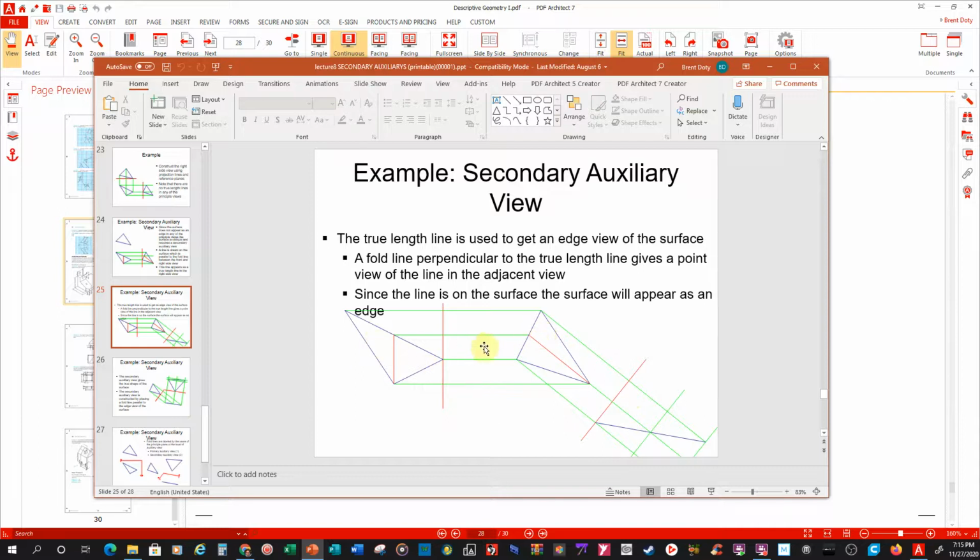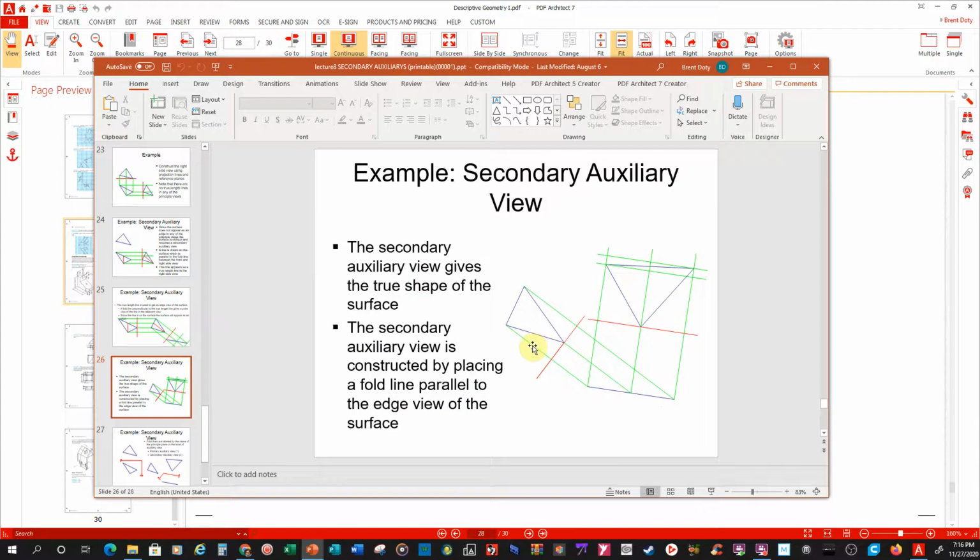I drew this view here, so that created this one. So when I'm creating this one, I'm projecting off of here and measuring from back here. I always try to tell people to go 2 back. But just remember, you can't measure off of the view you're projecting from. Okay? Basic rule. And we'll get to this in some other videos. And this one's gone on pretty good.